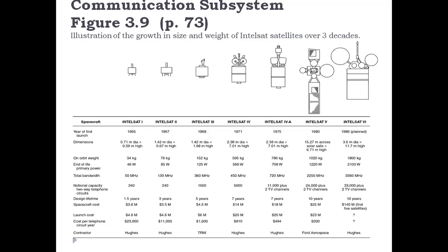The satellite transponders have limited output power and a station is 36,000 km away from a geo satellite, so the received power level, even with a large aperture station antenna, is very small and rarely exceeds 10 raised to minus 10 watt.